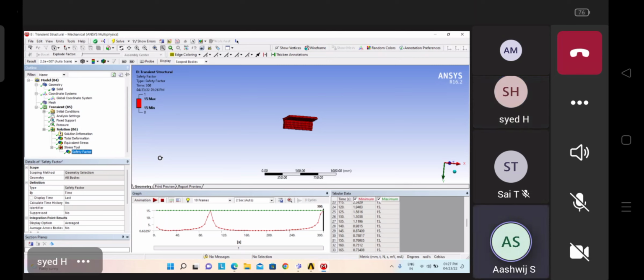I didn't get the last sentence you told about 3 times. See here, the value is 15, it is showing here now. The maximum factor of safety. So if I like to pass the test, the value of factor of safety should be around 5 point something, like 5.8. Then only we can say the analysis is a pass. Not exactly 5.5. If it is coming like 7.5, 8, also we can say that it is passing the test. Otherwise, if it is exceeding 10, we have to say that the object is failing here under those boundary conditions.